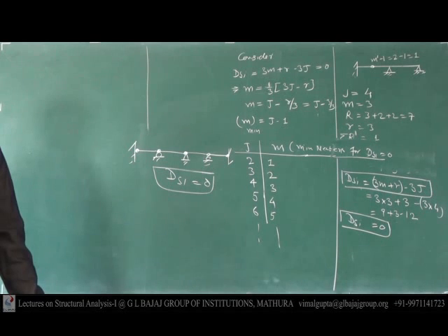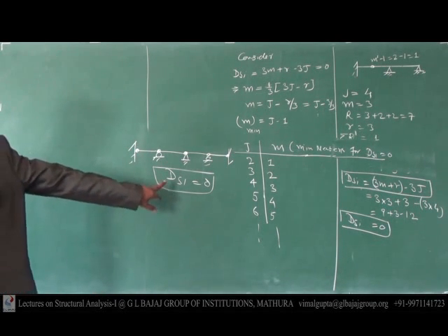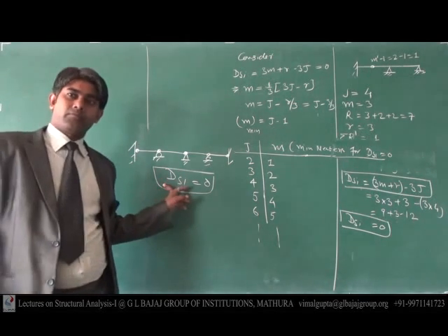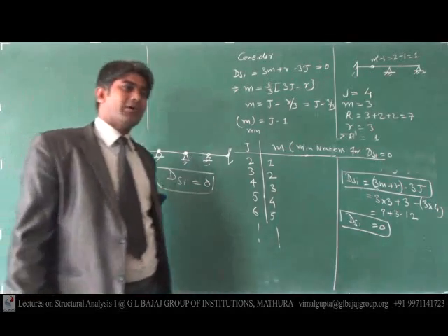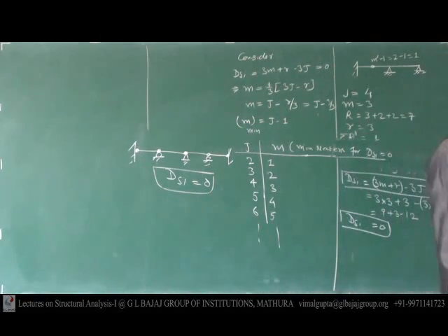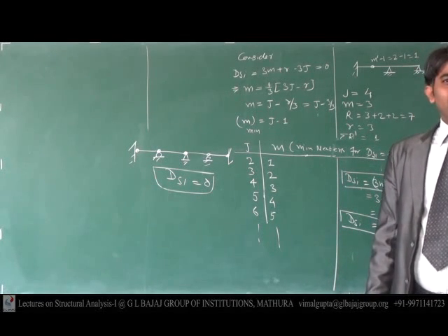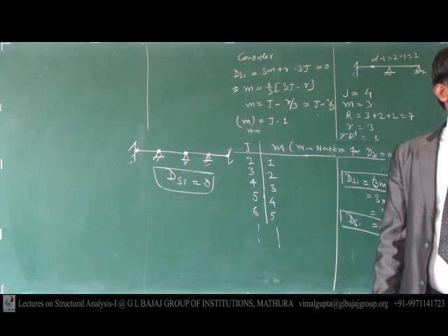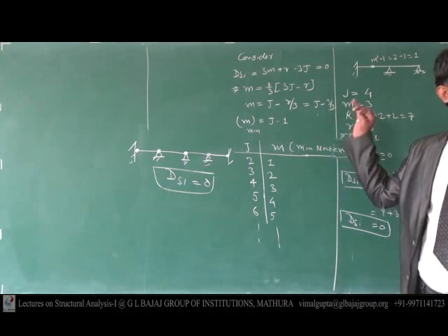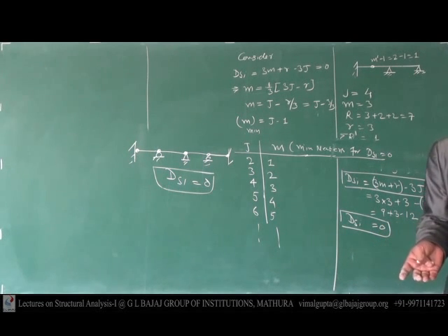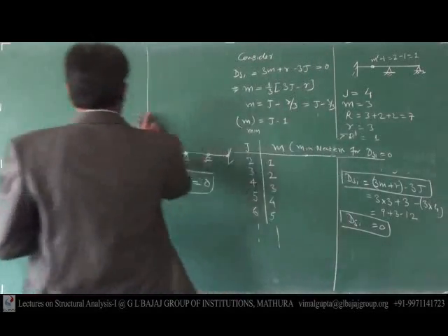Yes. Therefore, in case of beam, there is no need to find the value of DSI because it is a wastage of time. If you calculate correctly, then you will find the value 0. Okay, so static indeterminacy in case of beam is only external, and you know very well external indeterminacy.